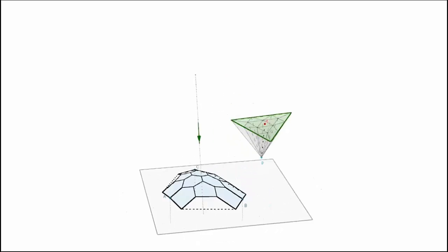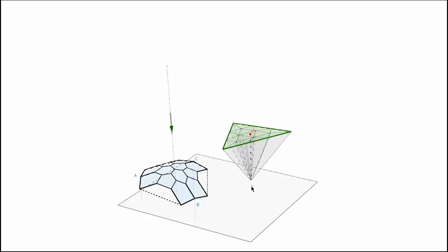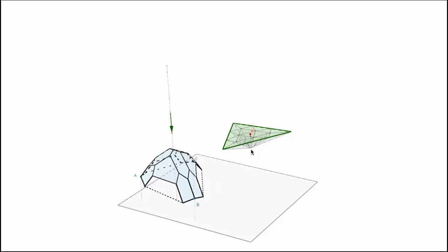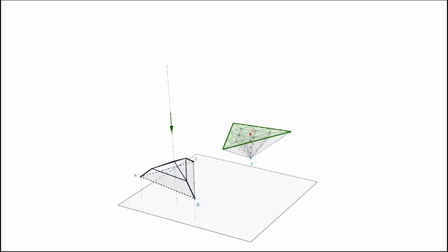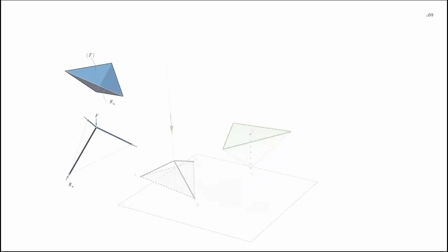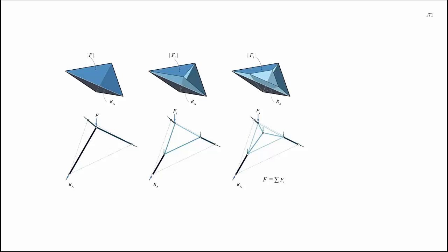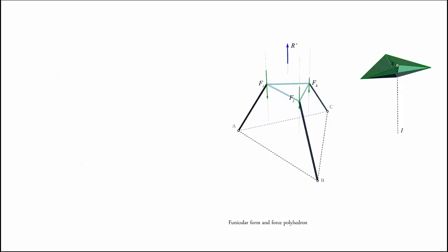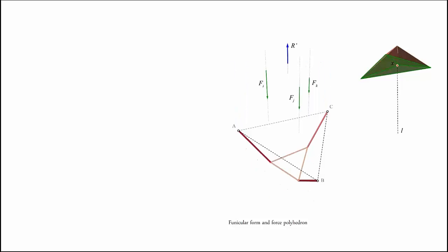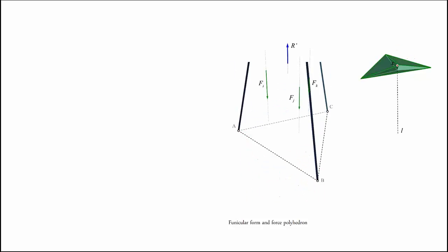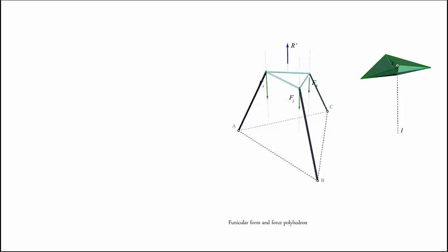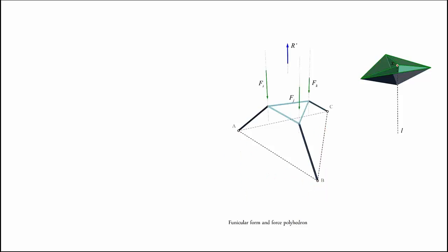Okay? So with a single technique, you're basically combining two difficult computational methods. The first one is form finding, and the second one is rationalization. So with this method, you're combining both, and the result would be fabrication friendly, right? Okay. So this is exactly the same principle. You can also use this technique in a constrained method. The same rules that people use in 2D graphic statics for the constrained construction of form and force diagrams, you have the same in 3D, which all of them apply, right?